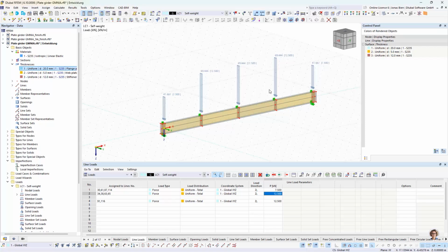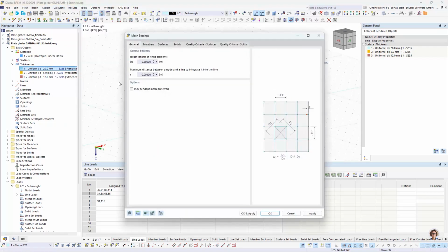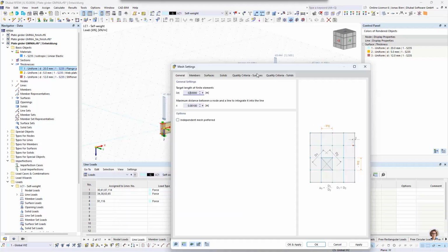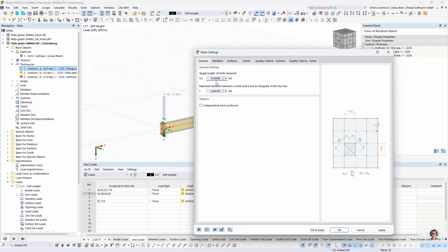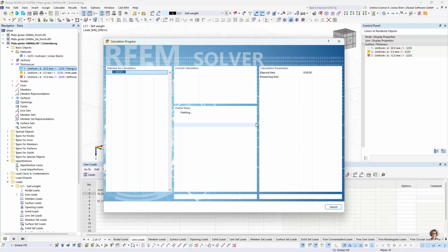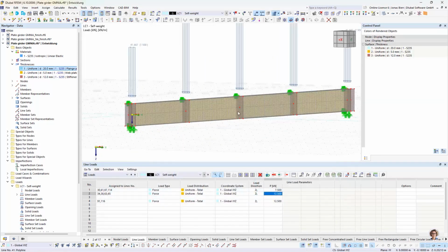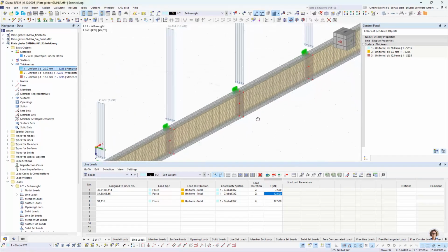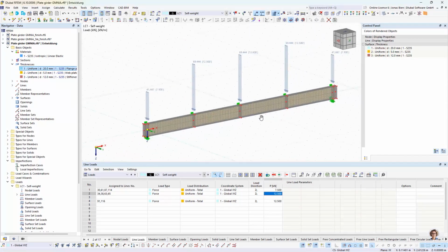Okay. Then one more important part when creating a surface model in the context of steel design. Usually our base settings for the mesh are not really suitable. This element length of 0.5 meter is more suitable for, I don't know, concrete slabs and foundations. So not for us. Otherwise, we would only have 1 or 2 elements over the height of our plate girder, and that wouldn't be sufficient to get a good model here. So we just use 5 centimeter in the first step and check the mesh visually to check if it is reasonable. And I think in the first step, this is all fine. It is always advisable anyway, in the context of a GMNEA, to make some sensitivity study of the mesh refinement at some point. But I think this is a good starting point here, this level of refinement.